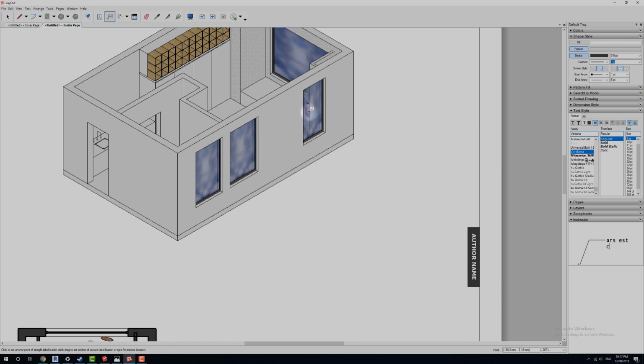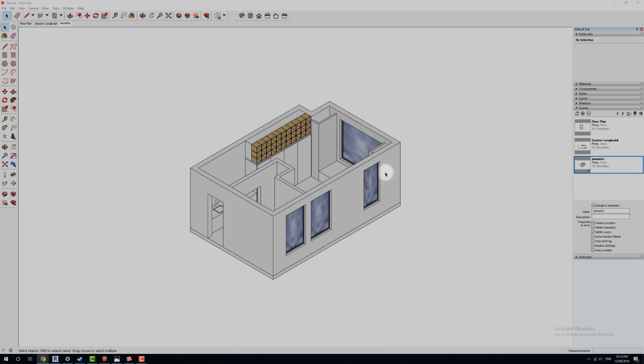So we're going to annotate this window. We start with the start point by clicking once and dragging down, there's our intersection by clicking again, and then our end point. I prefer these 90-degree angles. Now you'll notice once I've finished that end point, it's come up with a component definition. That's because over here we created this window in SketchUp as a component.